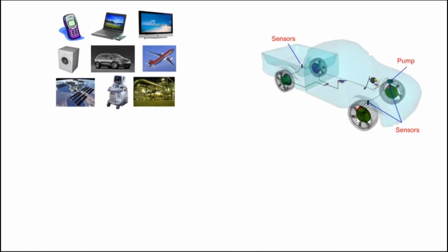The way the anti-lock braking system works is that we use sensors to pick up the speed of each one of those wheels. And then we have an electronic system which, depending on the speed of the different wheels, sends a signal to a hydraulic pump, which applies a brake to the wheel. Whichever wheel is rotating faster, more pressure would be applied to its brake, and the speed would be decreased. Thereby you could equalize the speeds of the different wheels and achieve much better performance. An anti-lock braking system is a common feature in many automobiles now.